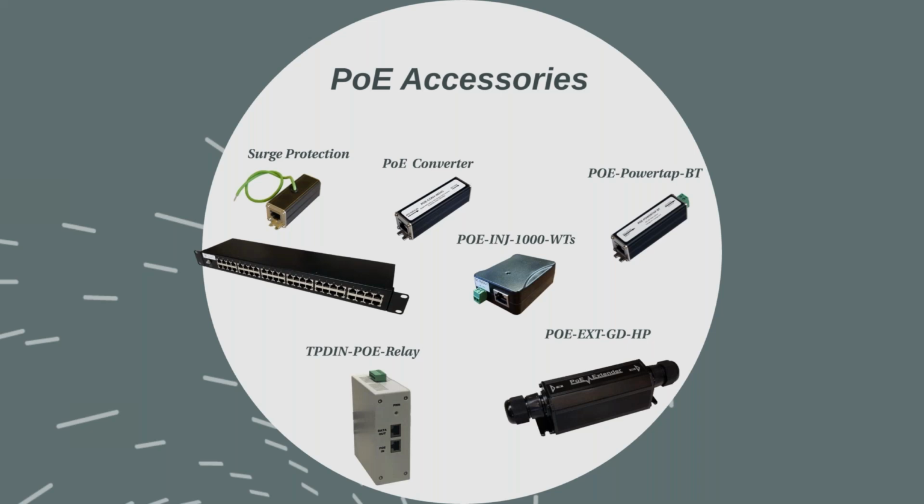We have a PoE converter. So this would be great. Let's say you have a standard PoE switch, which is 48 volts, but you want to power from that switch a 24 volt radio or 24 volt device, right? It doesn't have to be a radio. This little PoE converter can be in line to accept that 48, down convert to 24 volt at gigabit output. So it's just a nice clean device. All you need is a little patch cable to convert down to 24 volts.